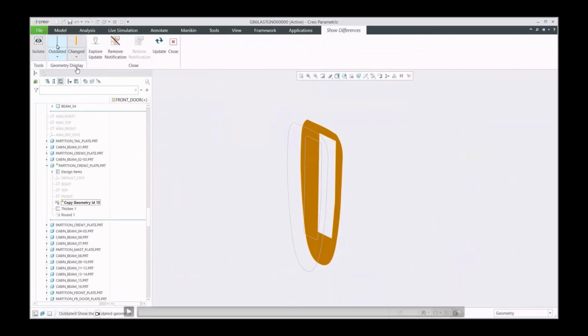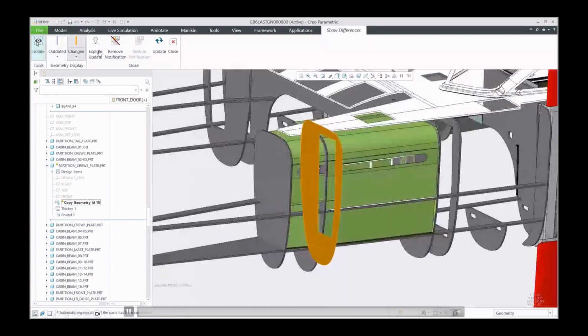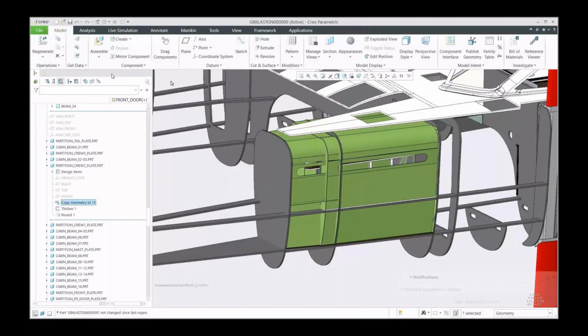So one thing you can do is fire up an on-the-fly design exploration session. It's basically a safe environment. It's going to open up a safe environment, apply the change, and you can interrogate it. If it does fail, you can maybe understand what you need to change to fix that. Or you could say, actually, no, that's gone completely wrong, I'll back out, undo what I did in the skeleton and start again. Or once you fix the change in this session, you can commit that change down to your local model. It's not something I'm showing in here, but that on-the-fly design exploration session can be really valuable for interrogating these designs, understanding them before committing to them completely.